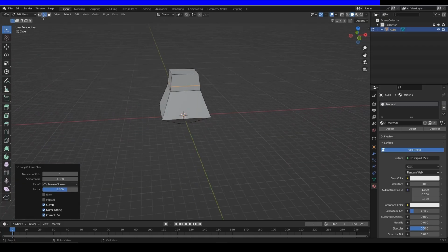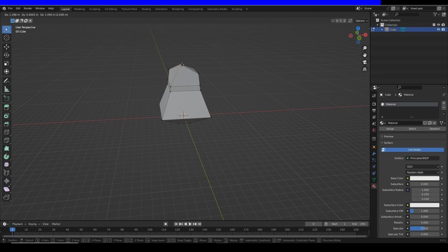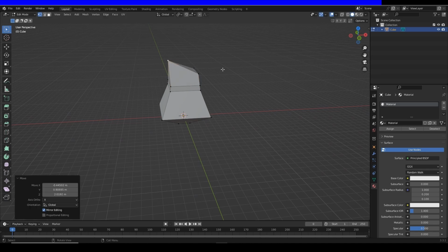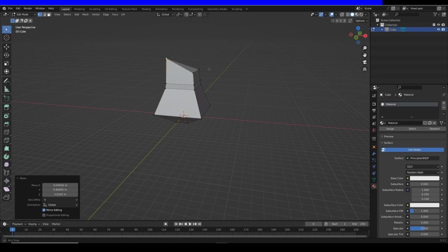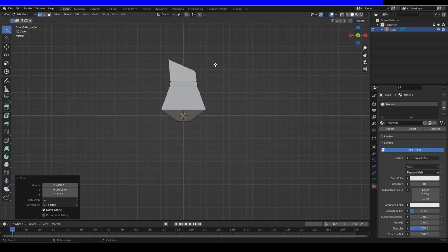Vertex editing is mostly about repositioning, and vertices don't have a rotation or a scale. However, we can add vertices by having it in the vertex selection mode and having nothing selected. From there, we can press Ctrl right mouse to add a vertex. We can also make a face from this. If we select these vertices and press F, it creates a face out of it.